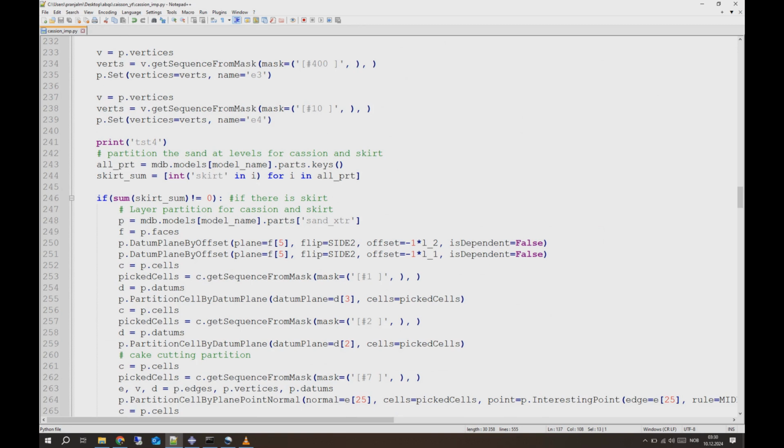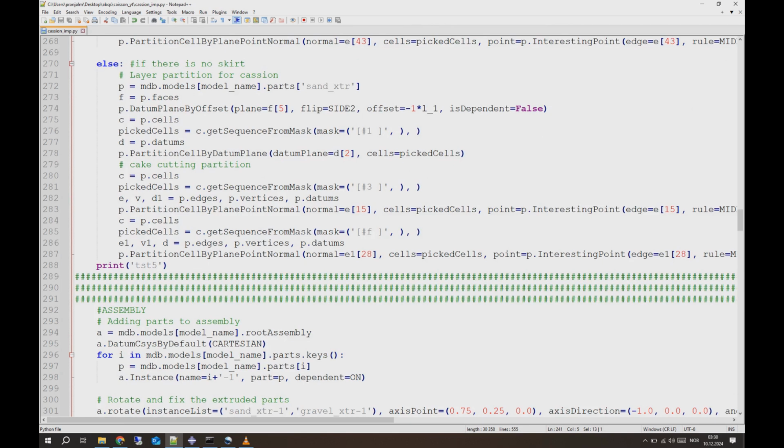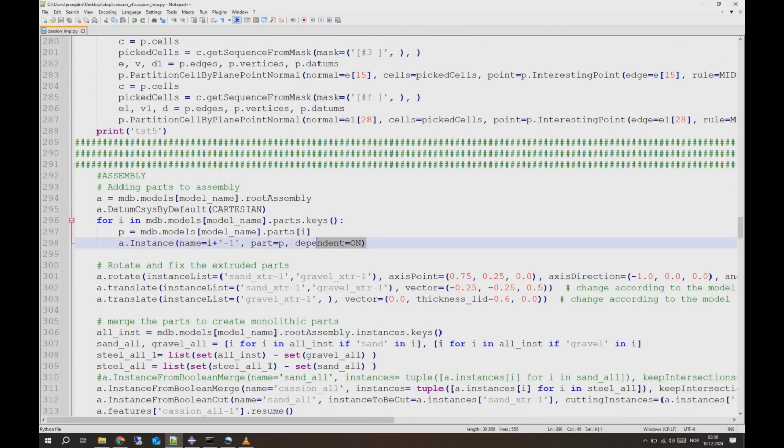There are several parts which I would like to cover here. As you can see, we can also put debug arguments. When we run the code, there is some printing argument. If there is some error before this, or something doesn't go after a specific line of code, we can just print. These are debug arguments. If you study Python, you will understand that if you want to see where the code stops running, you can just print something to see whether until that print the code is running or not. So this is kind of a debug. We check how far our code goes, and then we create the assembly at the end.